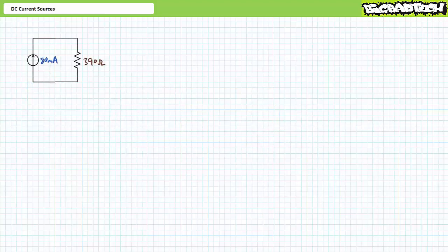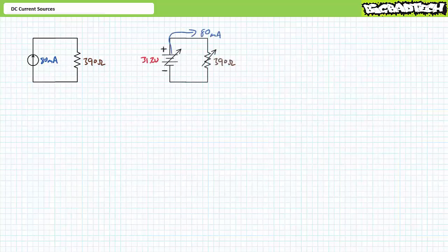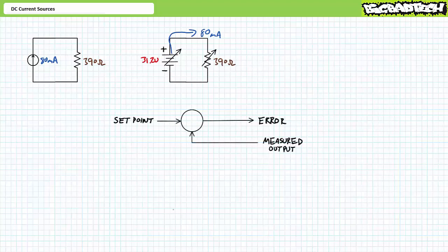Before we bring this short lecture to a close, let's pause to consider the means of operation and limitations of real-world current sources. As I mentioned at the beginning of this lecture, if you crack open a current source, what you'll find is actually a variable voltage source that continually monitors and maintains output current at some constant value. The means of doing this is via a closed-loop controller, one of the more basic elements of control theory.